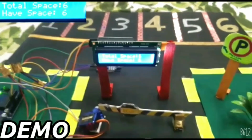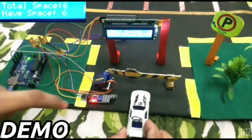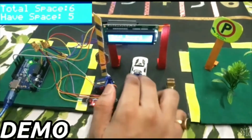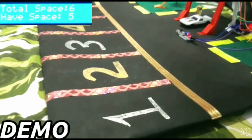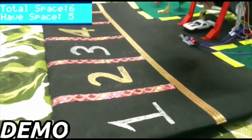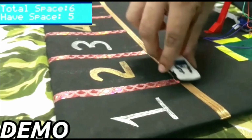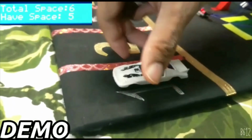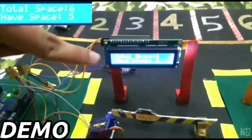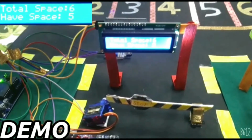So now let's take an example with a car. This first IR sensor will sense this car and this barricade will open. Now this second IR sensor will sense this car and ensure that the car is in the parking area, and this barricade will close. And we will park into the first slot. So as you can see, our first car is parked and have space is now 5. Similarly we can park all these cars in the respective slots.